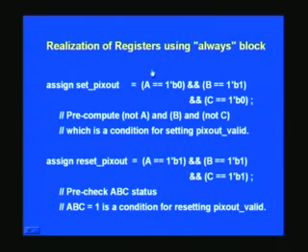Which is very much akin to what we have already seen here. Here the difference is A equal to 1, B equal to 1, C equal to 1, implying that it is ABC which we are ANDing together. And notice that in a logical statement we need to put double AND, right? Of course in an assign statement, even if you put just one AND, it still accepts. But as normal practice, you should use this, because in sequential circuits we can put the logic inside the always block. There, if you put just one, the tool will complain.